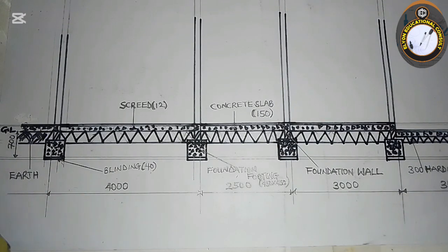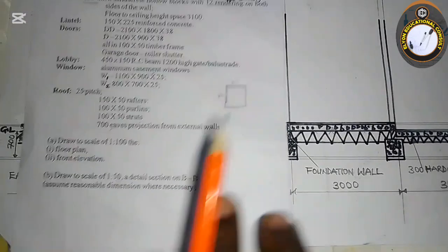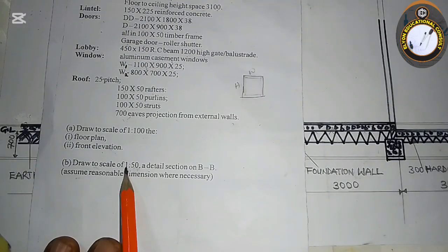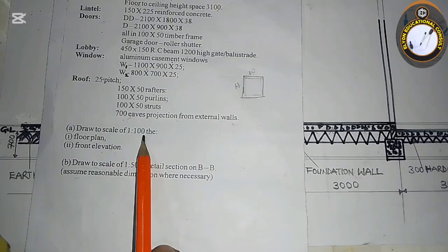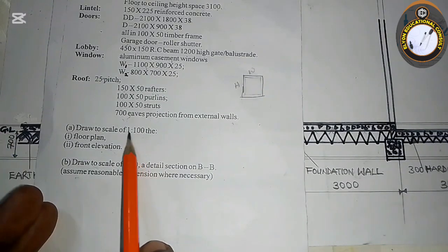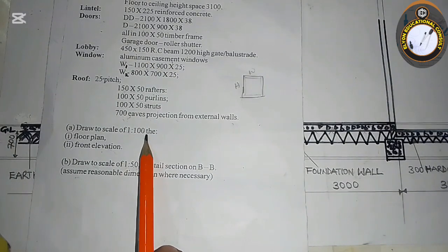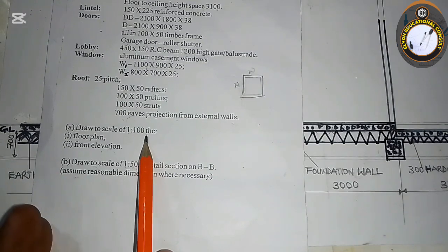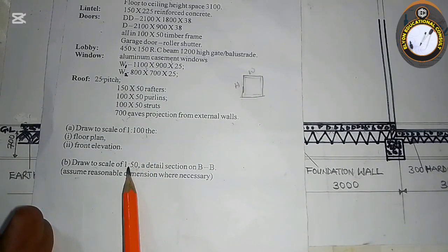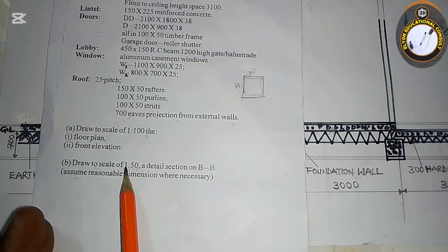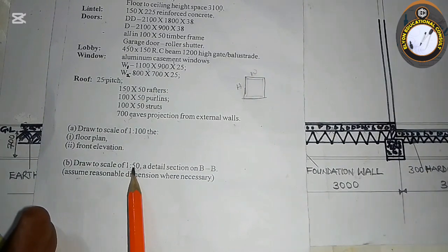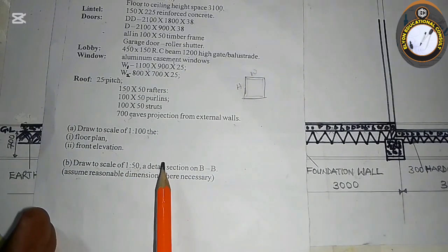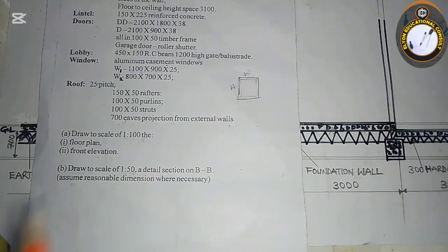So 3,100 divided by 500, because we are drawing to scale 1 to 50. That is why not 1 to 100 again, where we would be dividing by 1000 to convert to scale and to centimeter. Here we are using scale 1 to 50, so we are converting to scale, and also converting to centimeter because we are using a centimeter rule.